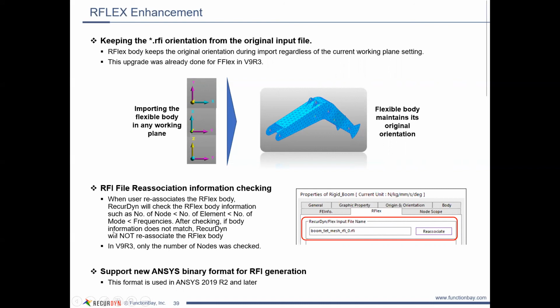In the past, only the number of nodes was checked to see if it was valid to use this new file. Now a lot more checking is done. It checks the number of nodes as before, but also the number of elements, the number of modes, and the frequencies.